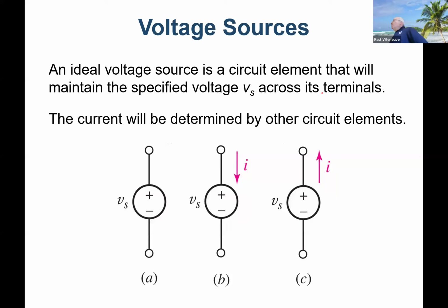All right, so voltage sources, easy peasy, right? We like voltage sources. The one thing that's unique about a voltage source is it dictates the polarity. When you have a voltage source, you have two things you have to provide. Number one is the magnitude of the voltage source. Is it 10? Is it 500? Whatever it is. And the other really important thing is the polarity, because the rest of the circuit does not determine the polarity. You, by plugging that in and connecting it a certain way, determine the polarity. So you need to specify the plus and the minus.